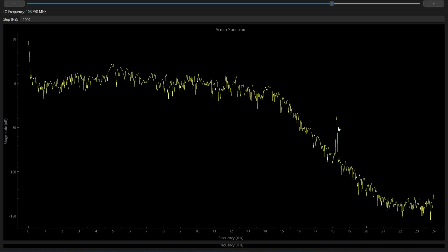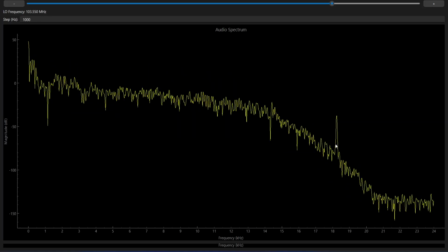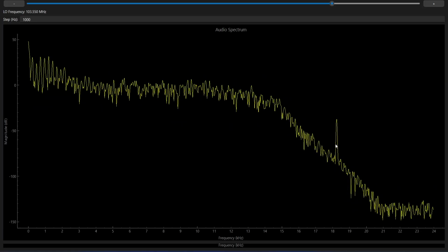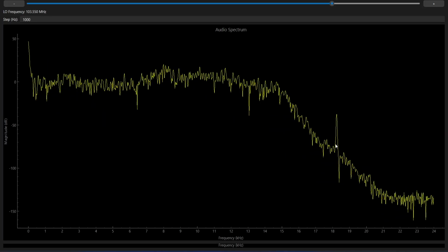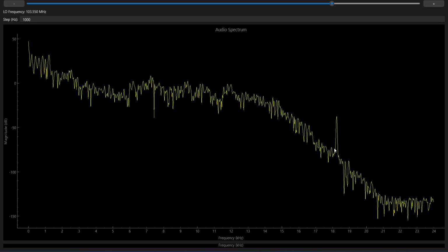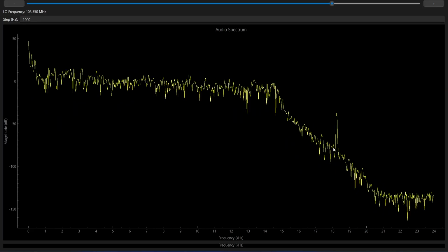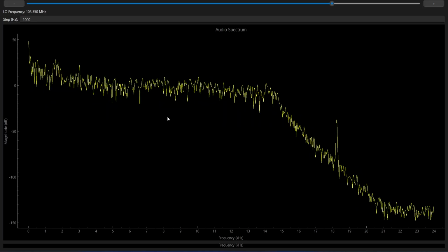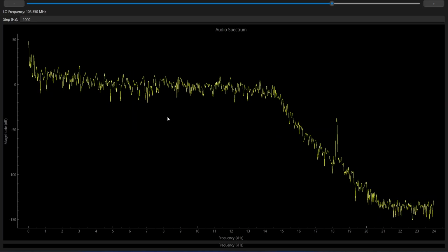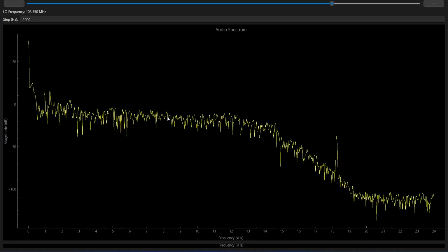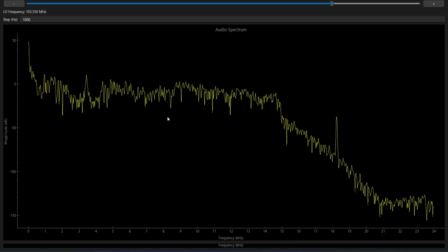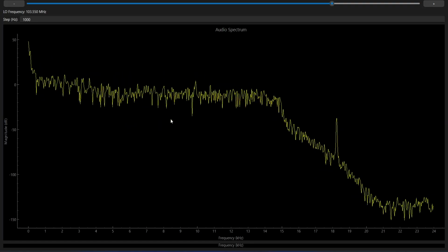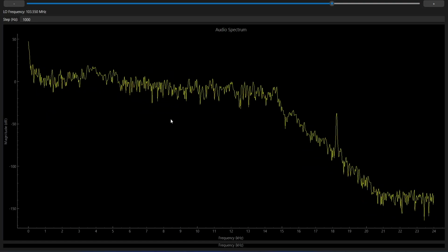Therefore, we can use this pilot tone and lock to 38 kilohertz, which is twice this frequency, to extract the other information at around 38 kilohertz, which is L minus R, because I talked about having L plus R before the pilot. In future videos, we will talk about how we can extract that, so we can extract L and R and receive the stereo information. But that's for another video. I don't want to make this video longer.